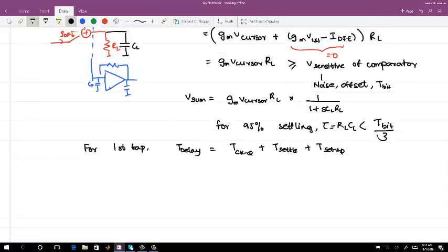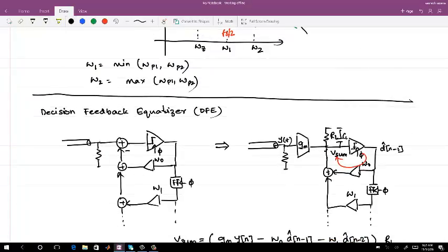So if you look, well, let me just show the block. You see when the clock comes, the comparator resolves that. But as soon as the clock comes, the output will not turn out instantly. There is a certain clock to Q delay for the comparator. And this clock to Q delay is dependent on the input swing, because this input swing is a small swing.